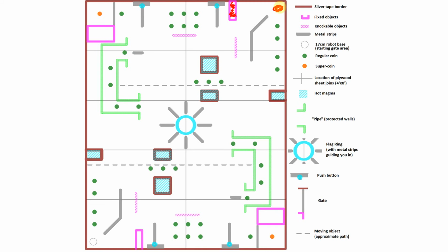When you set it down, you'll be able to set the direction so you might know which way it's facing. You might say, for example, that you want to drive this way to collect these coins until you get to this object, or maybe right in front of the object, go over this way, something like that. These distance sensors are useful because you could measure the distance between this wall here and where your robot is. If you know that distance, you can figure out, okay, here's where I am relative to that object. I know where I am within the course, and therefore I can turn and do some other stuff.